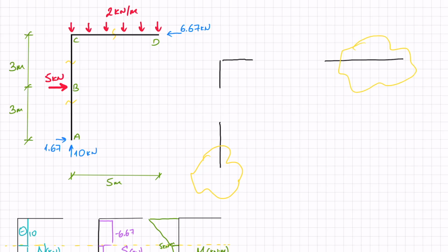Now, when we looked at the column part, we had a force in this direction, a force in this direction, and a moment in this direction. Now, this is internal, and that means when I make these cuts, I need forces of equal value but opposite direction on the other side of the cut, because when I put this all back together, these have to disappear.